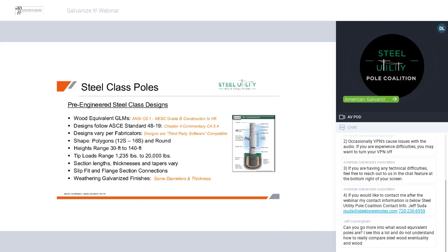So this is kind of a takeaway of pre-designed structures. The wood equivalency is a cautionary term. It's terminology that exists, but please be mindful of the instruction or guidance in the commentary of 4819. So there are a lot of definitions and a lot of things to consider in equivalency. The best way to sum this up, the last 2 slides really walk you up to a methodology or a starting point to design the pole. You need to have some sort of basis of design. And what it comes down to is ANSI wood across your NESC material code factors across an embedment.